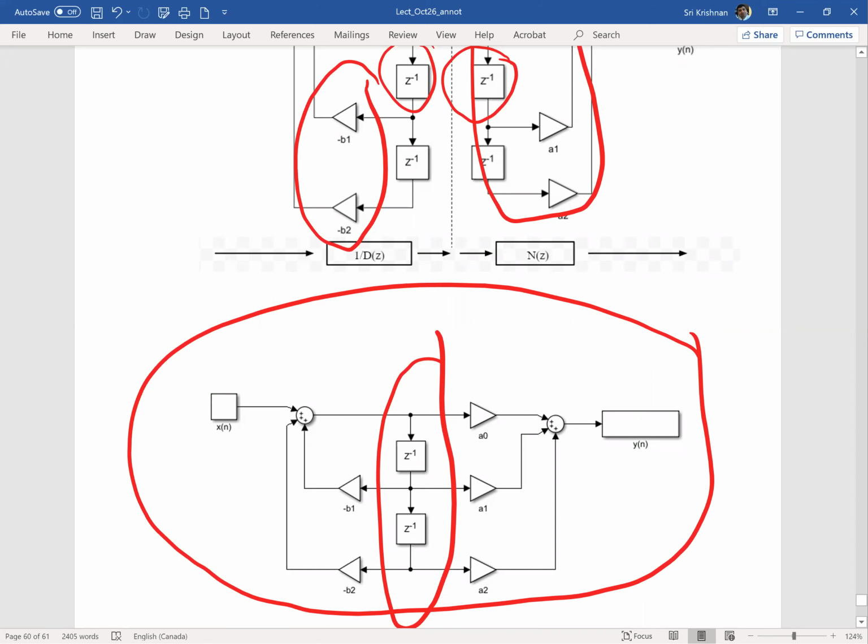Now with the direct form 2, just by flipping N(z) and D(z), we have got into a compact representation, saving 2 delay elements. The number of multipliers is still the same, 5 multipliers, but one additional thing is that we have added one adder. Okay, so now you are getting an idea that the hardware resources could be optimized by simple rearrangement of the configuration.